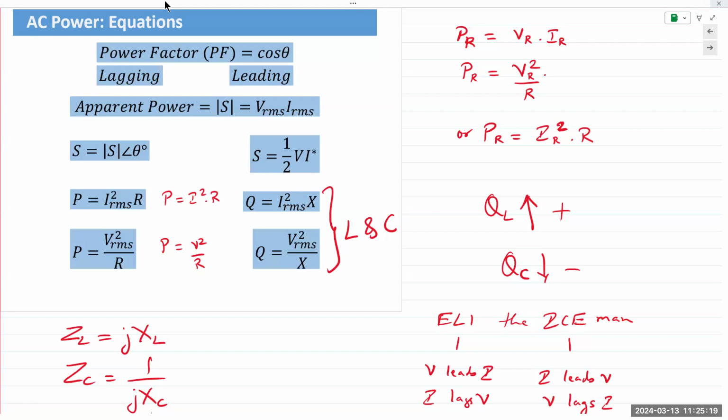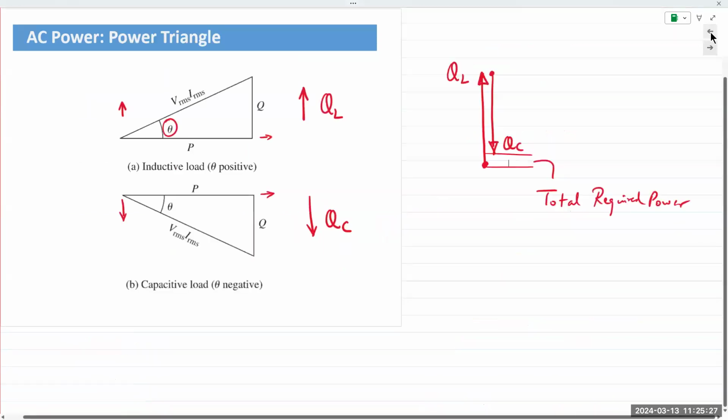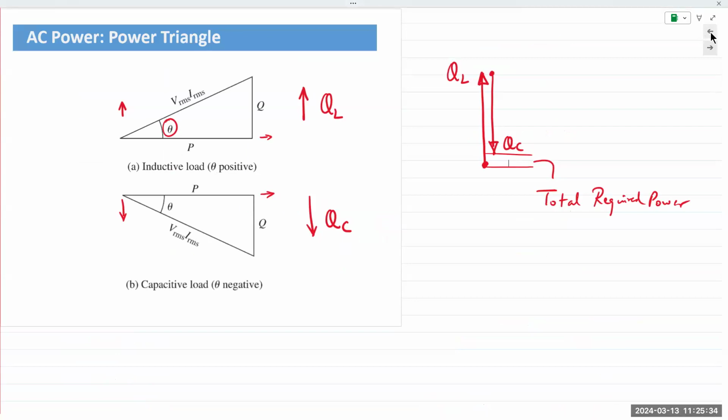Okay. Total complex power is a complex quantity, so you can plot a triangle, which we saw in the previous slide. You have the real power P on the x-axis and the reactive power Q on the imaginary axis. If you join the 2 points with the hypotenuse, you get the magnitude of the complex power.